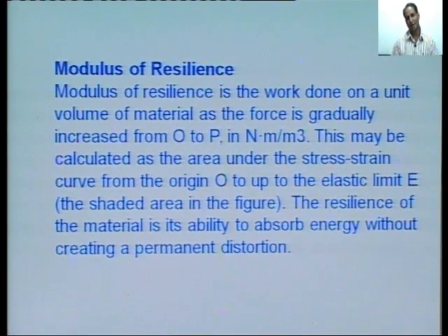And then I will also define the modulus of resilience. Modulus of resilience is the work done on a unit volume of material as the force is gradually increased from O to P. This may be calculated as the area under the stress strain curve from the origin O up to the elastic limit point.